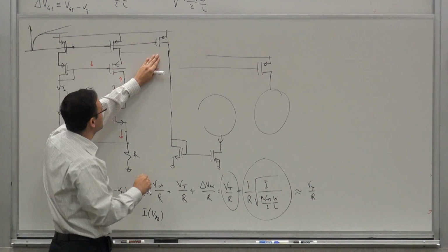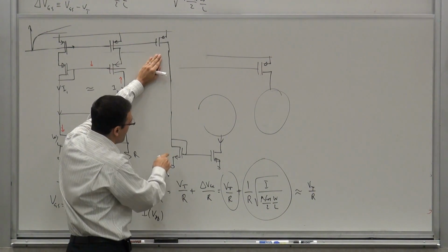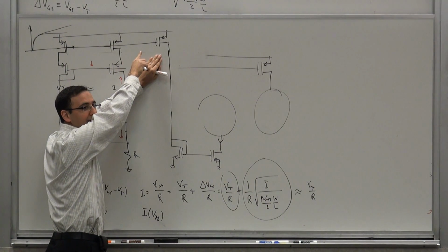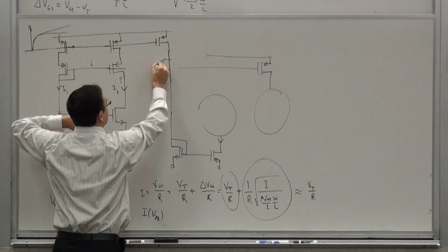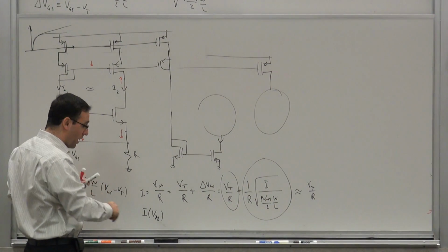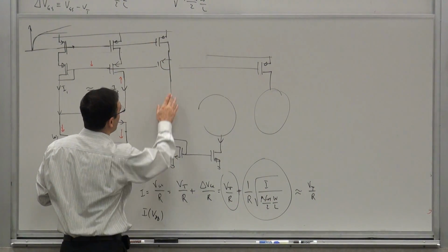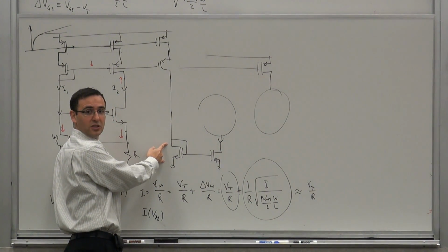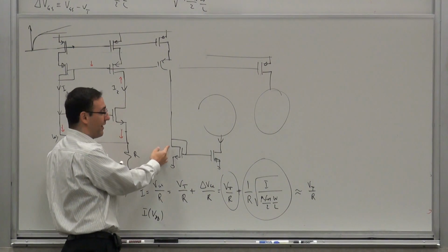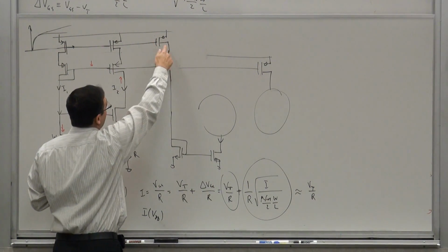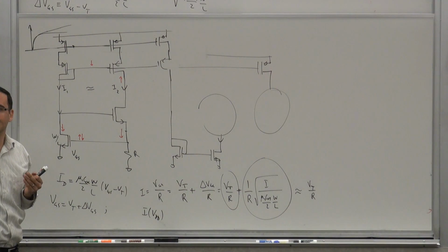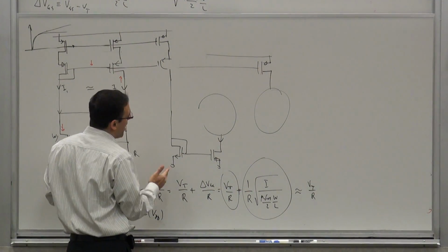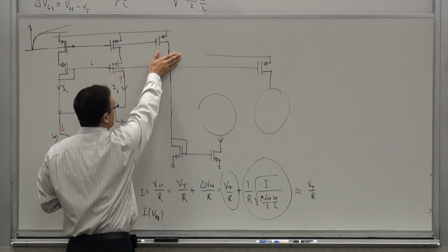Because if your output resistance, for instance, if you don't do it that way, if you just take this, then this current would be more different from that than it would have been if you had this device. But this can vary more. Now, in this case, I would prefer to have this Cascode because I know this voltage is a fixed rate. This is like a VGS above the ground, and if I have enough headroom from the ground to the VDD to carry this voltage drop, then this is better because this guarantees more uniformity in the current between this branch and that branch. But if I had a problem for some reason and didn't want to use it, I can just basically drop this.